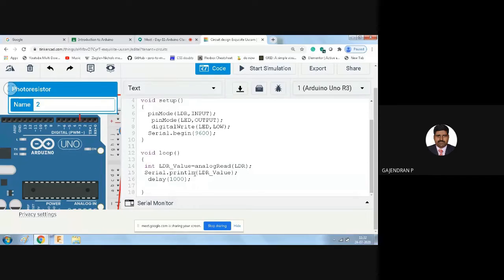What do I need to write? Please come down here. See, there are three conditions. Let me first initialize the first condition. For dark mode, if my LDR value for dark condition is 54, I'm going to give a certain range and operate in between that range.